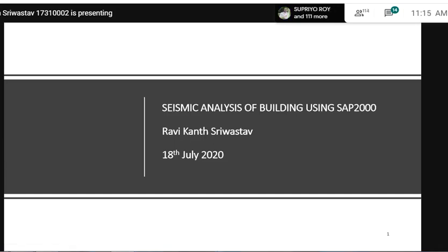You have definitely covered RCC design, in which you must have learned how to design beams, columns, foundation, beam column joints. Maybe beam column joints are not covered. So my coverage will be how to analyze the building, how to obtain the design forces. Now I will take each point in very detail. If you know for what forces you need to design each element, the designing becomes very easy, right?